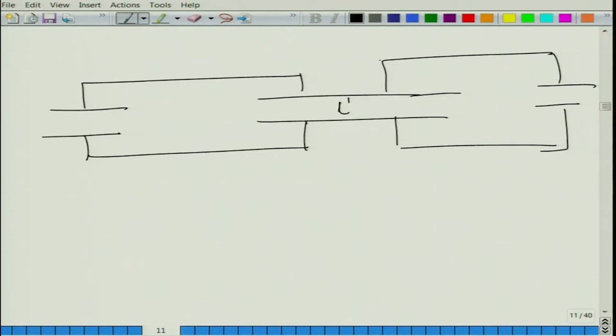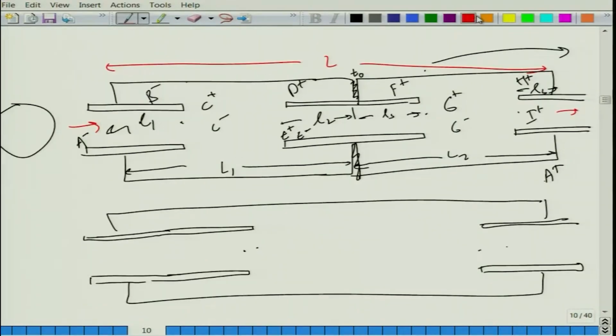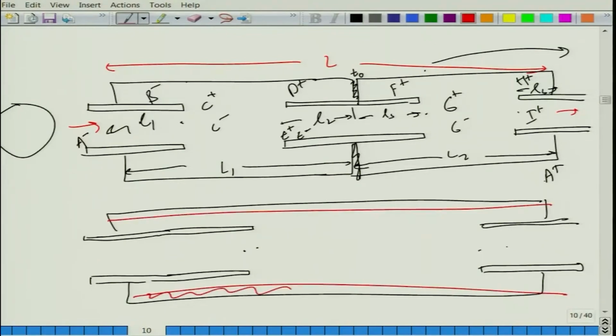especially when you have one other thing that you can do, which is possibly to have some sort of a lining on both sides of the circular duct, and these are hybrid muffler configurations. These linings can really kill the high frequency noise. The moment from which the muffler starts exhibiting very peaky behavior, with a number of troughs and domes beyond the cut-on frequency of the 0-1 mode, those modes can really be controlled by incorporating this lining, and that can really help you. So, the higher frequencies can be completely killed off.